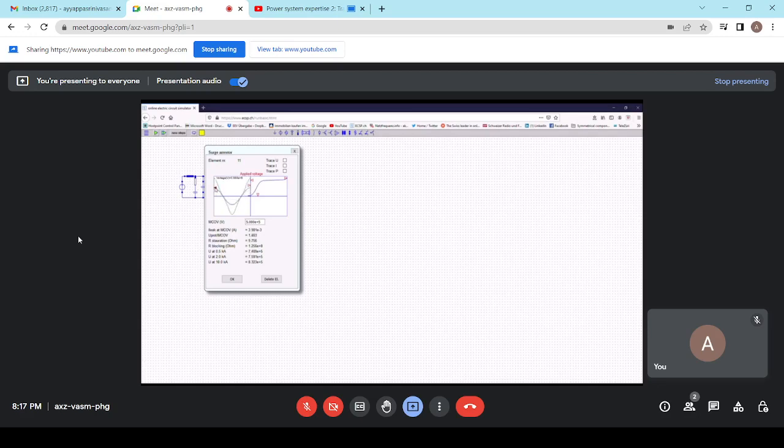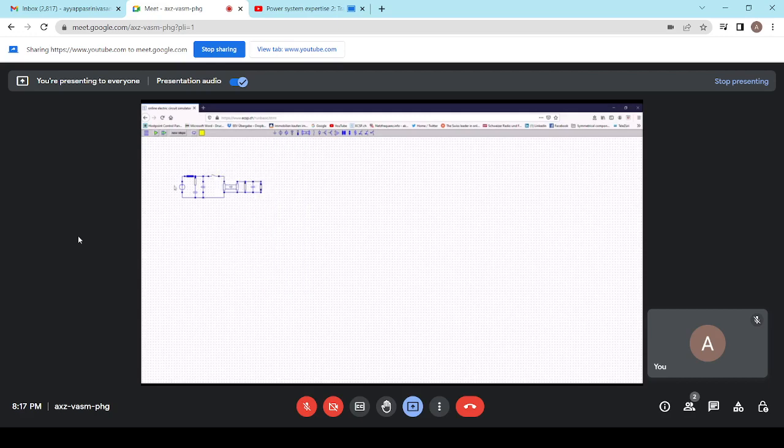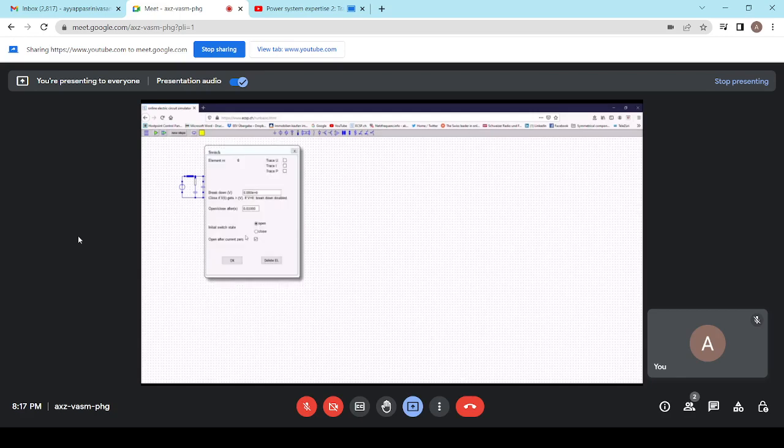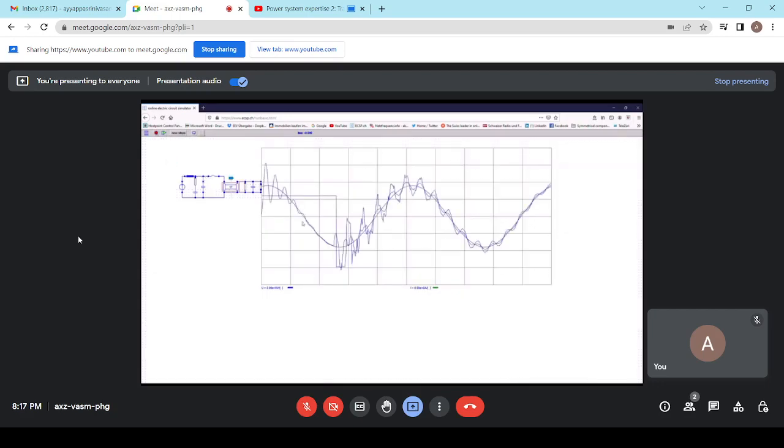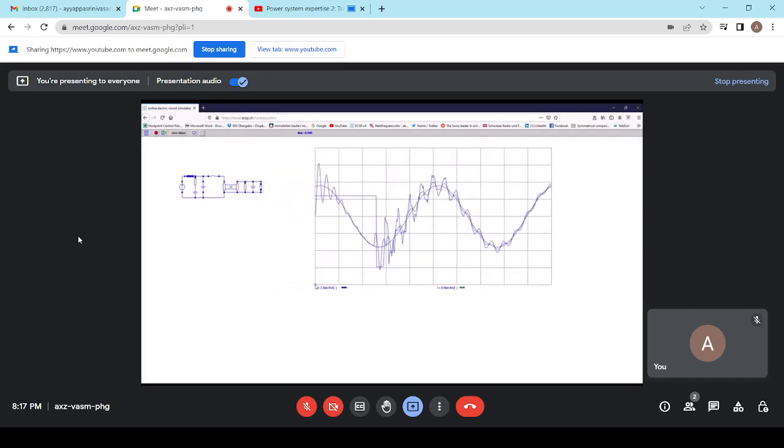This one is just to check the impact of the voltage on the current through the arrester. Let's leave the rest as it is and see the impact it has on the overvoltage. I also remove this trace here. You see, the maximum overvoltage is now lower than before. Let's now compare the impact.